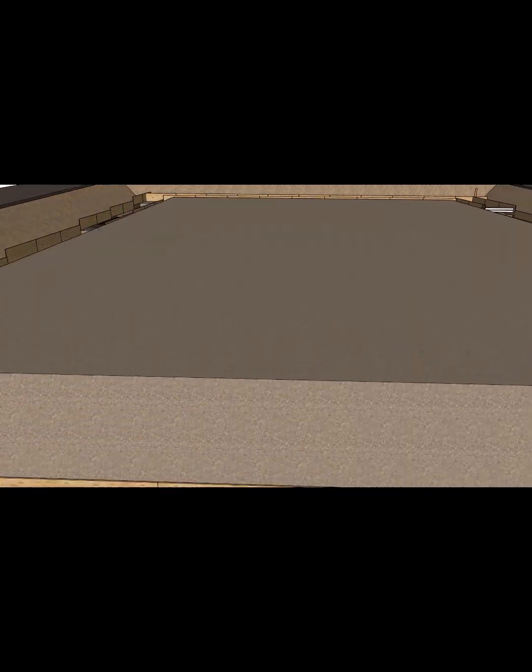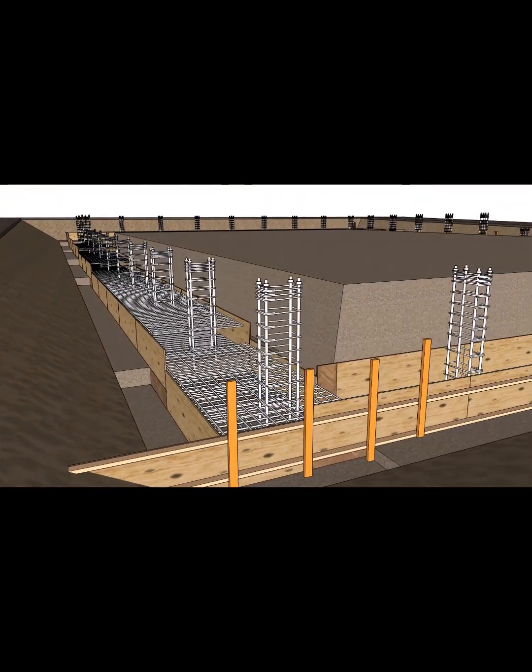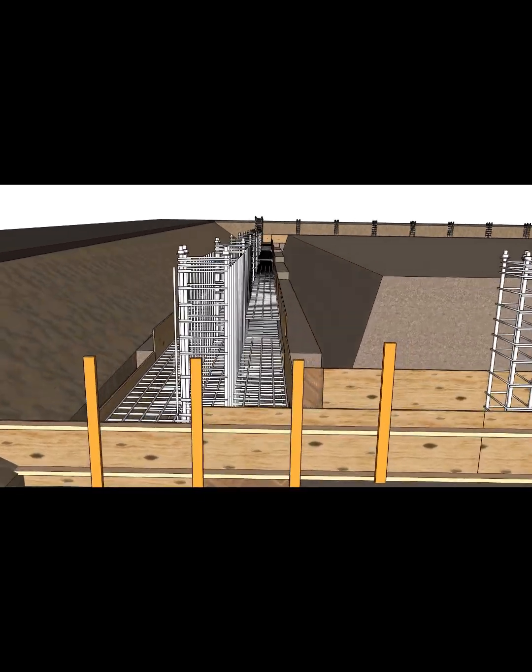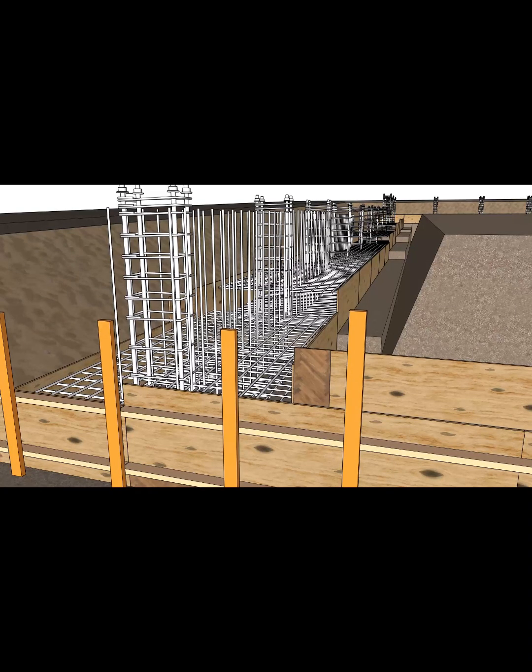Lamb and a rebar company will work together to install the reinforcement and plinth cages. Rod busters will place the bottom mat. Lamb will install the plinth cages on center both ways and to elevation. Bolt bottoms must be off of the dirt by at least 3 inches. They must be embedded in the footing by 1 foot. Rod busters install the top mat, corner bars, trim bars, step transition bars, and wall dowels. Lamb will install the keyway and wood templates. We will ensure the plinths are in the correct position and elevation before inspection. Rebar inspection. Then place the concrete and strip.